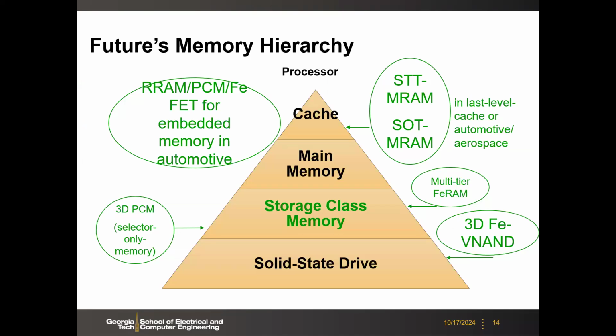For example, RRAM, phase-change memory and even FE-FET are suited as embedded memories, especially for automotive electronics, because many automotive products use an MCU, a microcontroller. A microcontroller has NOR flash or embedded flash, eFlash, on chip.